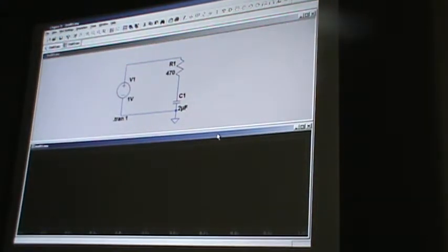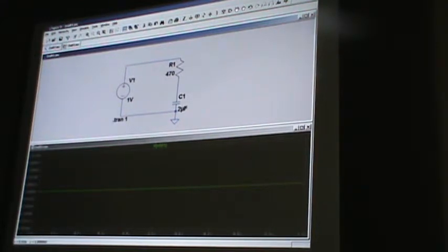And here we are, and we've done a simulation. After a simulation, things kind of change a little bit. You click on your schematic and go over a wire, and it becomes a probe. You click on that, and it draws the plot of that versus time. And of course, this is at 1 volt. This one is also at 1 volt, or so it appears.